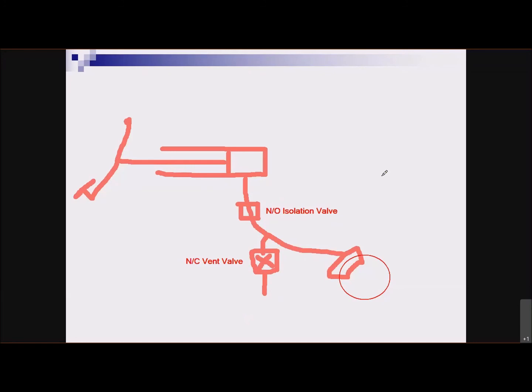So you're going to just have normal braking or non-ABS braking. If you pull the ABS fuse, for example, these solenoids will be in their normal position, right? That one will be normally open, fluid will flow through it to the brake. This one will be normally closed. No fluid pressure will be dumped from that brake line. And this can happen over and over again, very, very rapidly, to where you hear it and you can feel